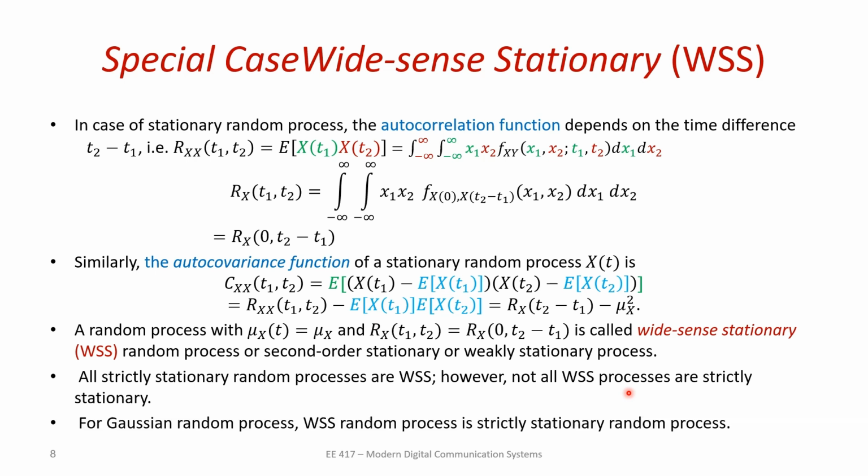That's logical. And we also can say that the Gaussian random process is a special case. If you know it's wide-sense stationary, then you can automatically conclude it's stationary in the strict sense, because a Gaussian random process is only defined by the mean and covariance. If those two are stationary, everything else is going to be stationary. So you can think of this as a special case.